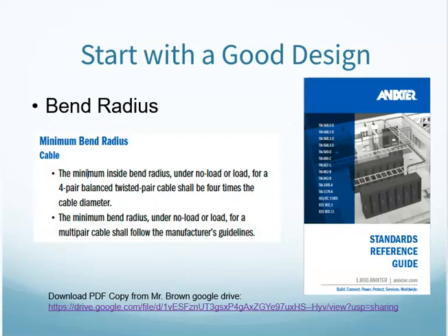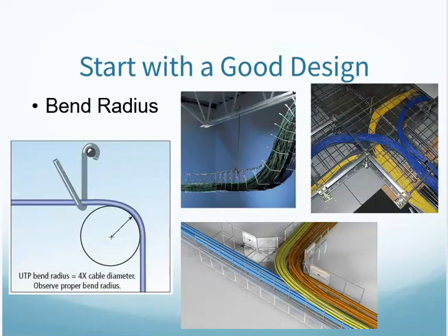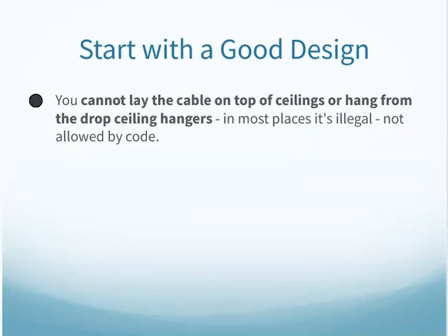We should be paying attention to bend radius. As we're installing cable, use nice gentle bends, making sure we don't have a tight bend around a corner that'll deform the wire twists inside the cable and potentially cause interference or noise at that bend.